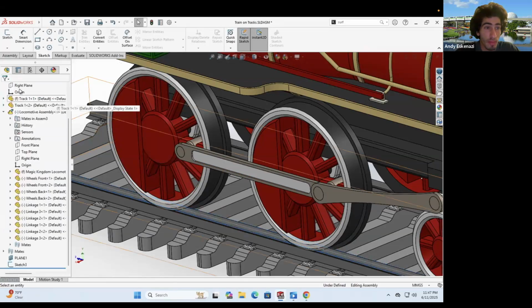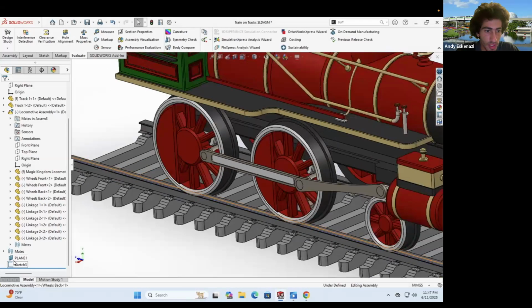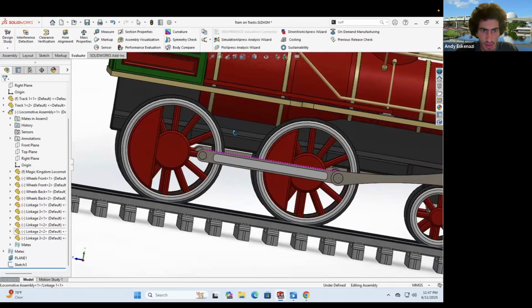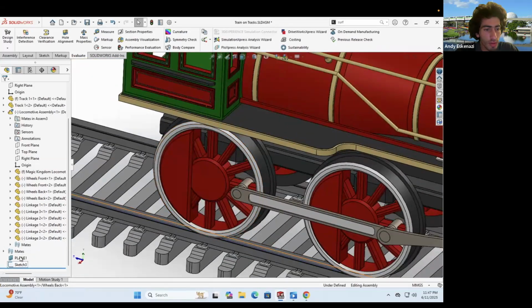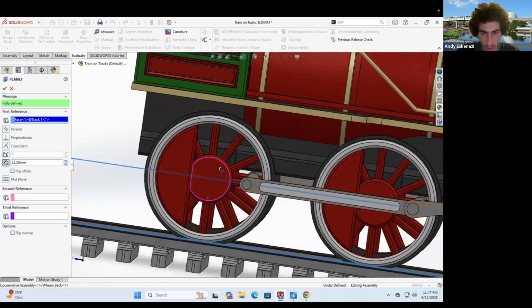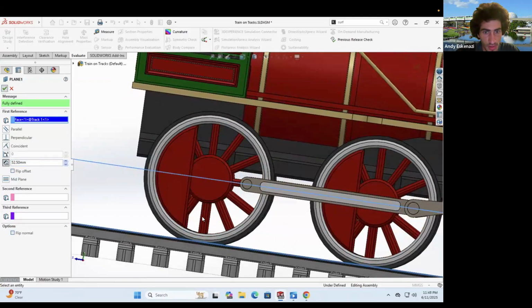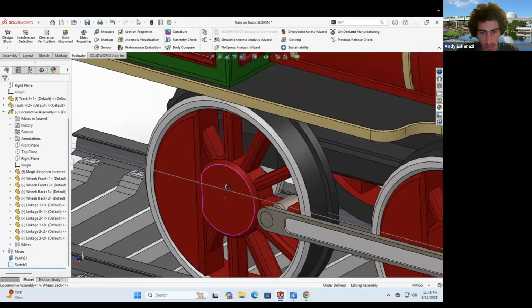And I do not remember, the only way to figure that out is by going here to evaluate, measure, and that guy is 105, which means, is it 105? That's interesting. So if technically I go here to the plane and I make that 105 over 2, does that bring us to the middle of the wheel? It seems like it. I'll click on save. I do have that.